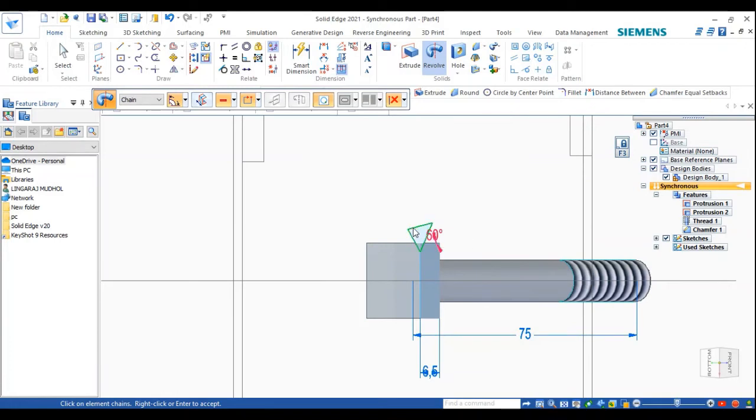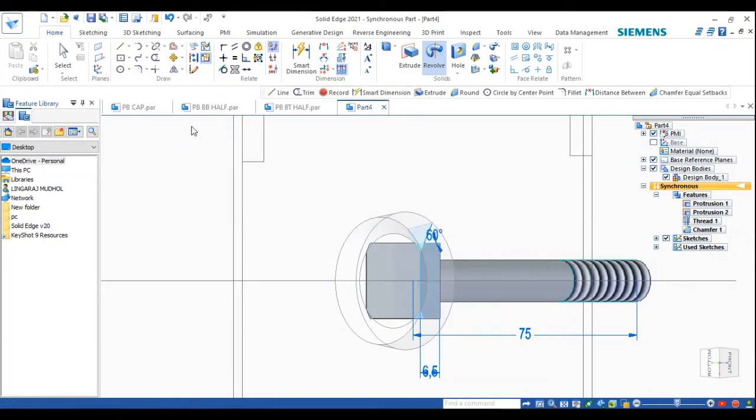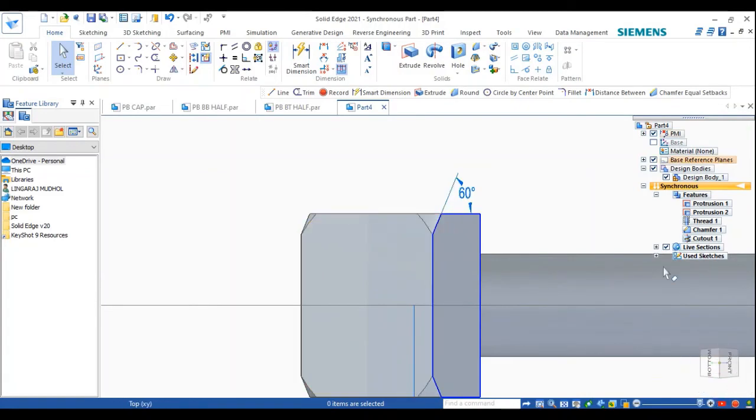We'll click the sketch you want to revolve here. The axis is a central one here. We'll get, but we want it on a full 360 degrees, so here there will be an option called 360. Just click here. See, you'll get the chamfering.